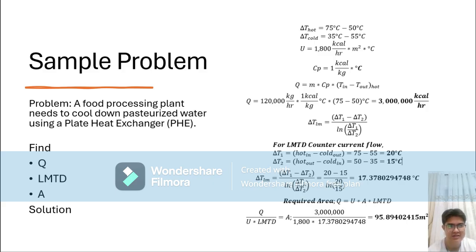That is why thin metal plates are used to, let us say, gimmick physics to get better heat transfer, because there's less thickness, less thermal resistance, while at the same time giving our fluids more area to transfer their thermal energy to. So that ends our report for plate type exchangers.